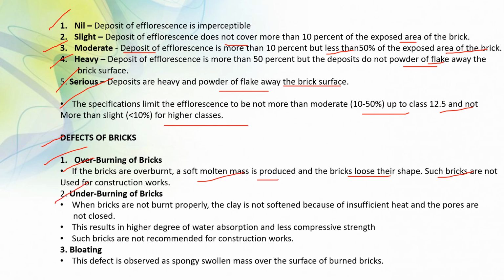Next, I will discuss underburning of bricks. When bricks are not burned properly, the clay is not sintered because of insufficient heat and the pores are not closed. Next, this results in a higher degree of water absorption and less compressive strength. Such bricks are not recommended for construction work.